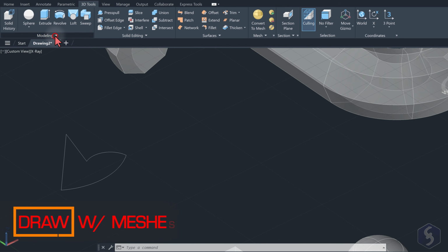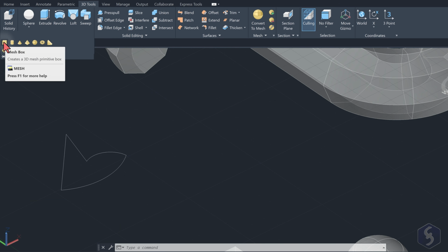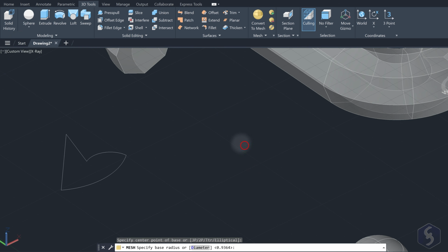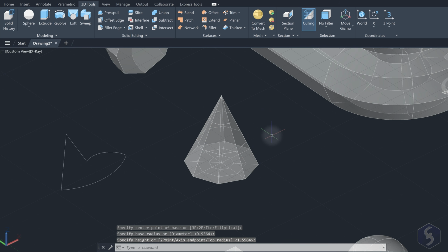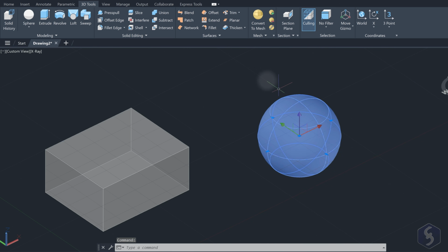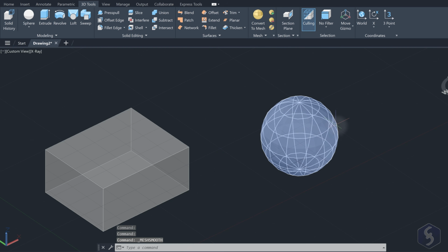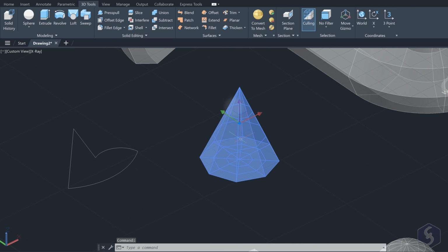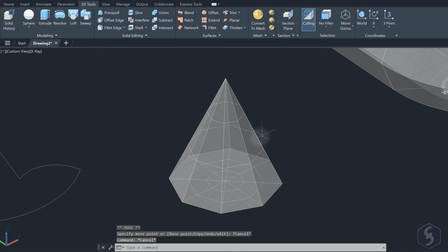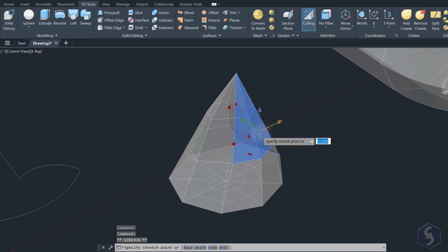To build very custom 3D shapes, you have to use the 3D meshes, such as objects made of smaller polygons that you can edit individually. First of all, drop a mesh to start from with either any mesh tool from Modeling or by selecting any 3D solid and going to 3D Tools, Convert to Mesh to get a mesh from such solid. At this point, you can select the entire mesh to edit it with its gizmo, or hold down the Control or Command key to select and edit specific polygons with the gizmo. This way, you can customize the mesh shape as you like.